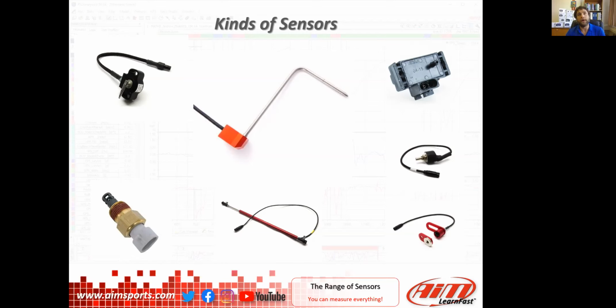So it's a really nice way that makes our job doing this kind of custom sensors much, much easier to work with. And then someone asked about the temperature sensor I showed, is it better to configure a Bosch one or a GM one? Many times they're the same. The more important thing is to make sure you can get a sensor table for that particular sensor to be able to put in. So already some really awesome questions that we have going here.